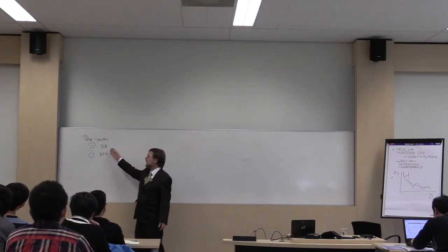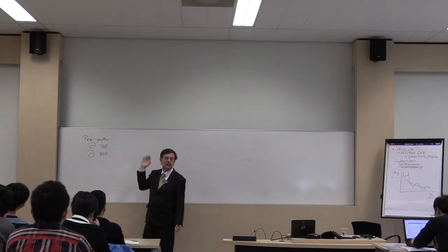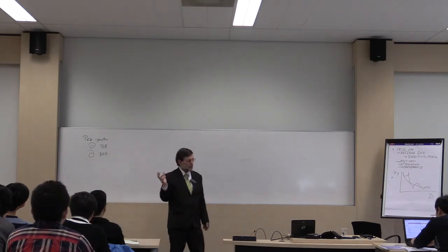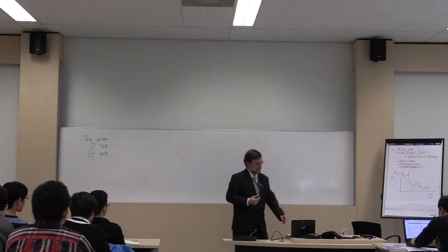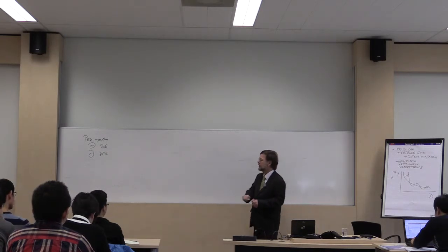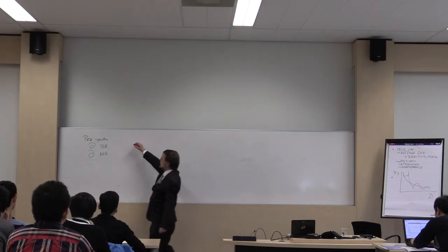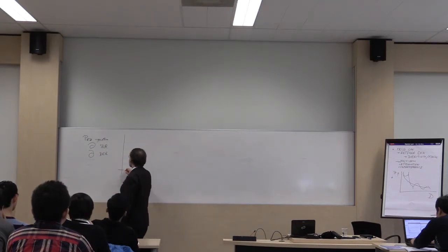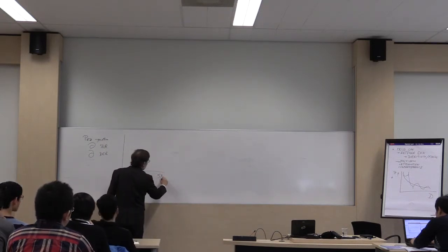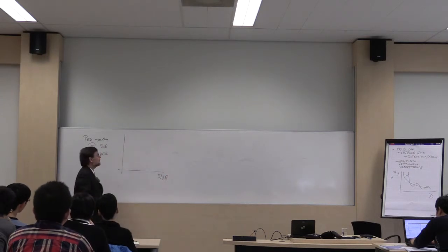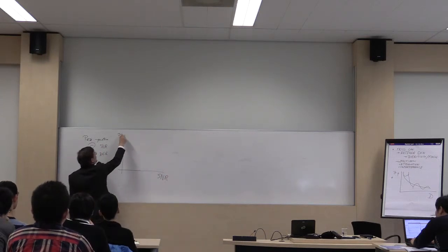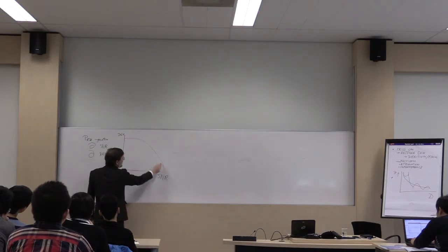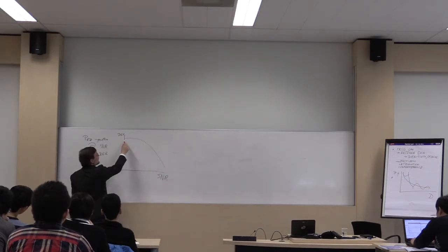That is also directly related to the signal-to-noise ratio if you know the modulation. Because for any kind of modulation, you can find in literature what's called the waterfall curve that relates signal-to-noise ratio to the bit error rate. And these curves look all like this, and with some variations.